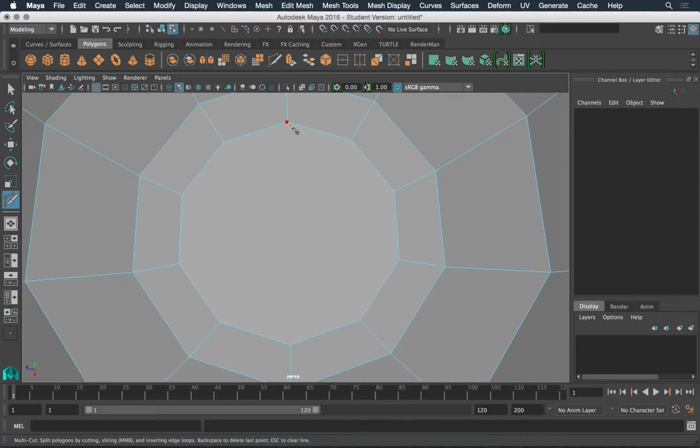So I'm going to go up to this one, click when it turns red, and then I'm going to come down to the one below it and click. It drops an edge in between, hit enter. I made an edge right there. Do the same thing. Anything that's across from each other, I'm going to connect them. So this one to this one, kind of like a spider web, hit enter, and then click to click, enter.